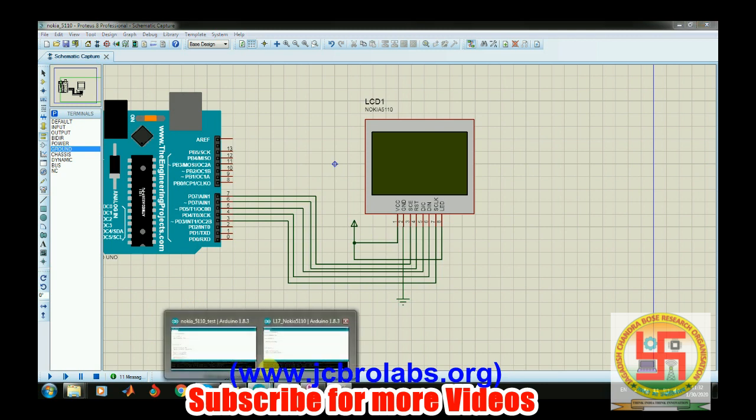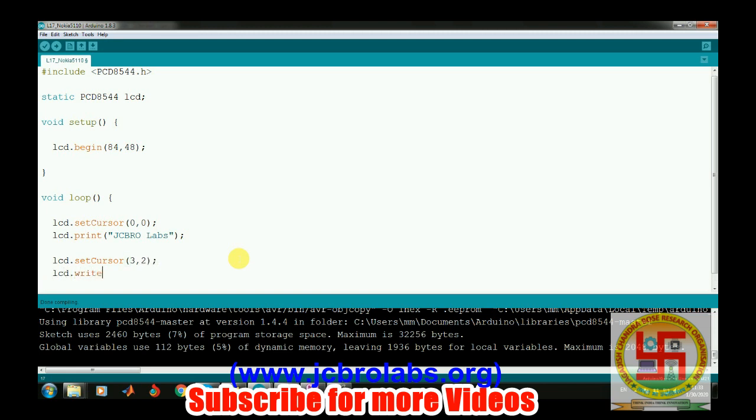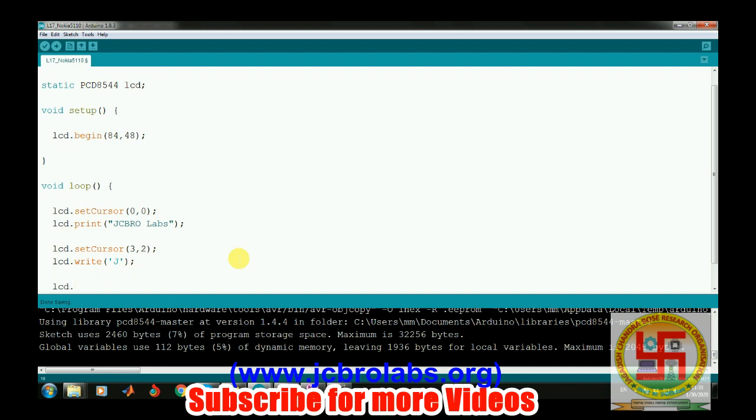Let's write something else as well. Okay, so now let's say we want to display a single character. So we'll set the cursor position to, let's say, third column. So it is pixel wise, remember. Okay, and then row number 2, and then we'll write LCD dot write. If you want to display any single character only, we have to use this LCD dot write command. So here let's say we will display J.